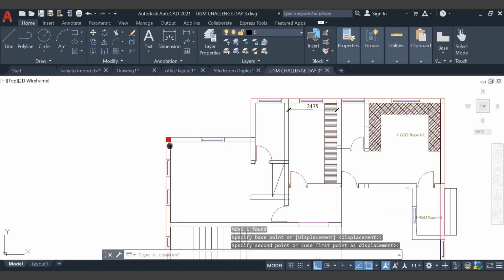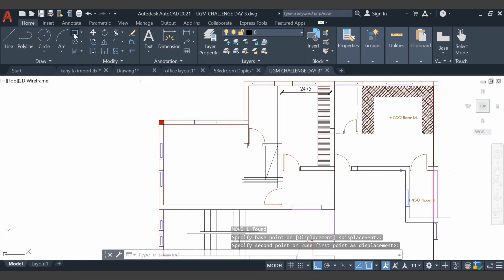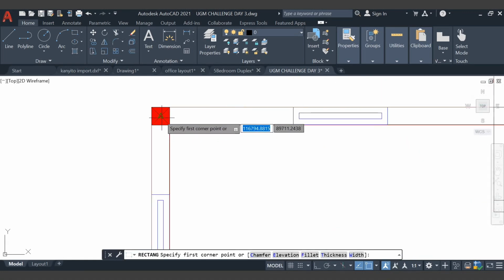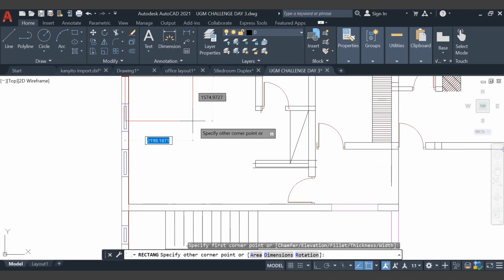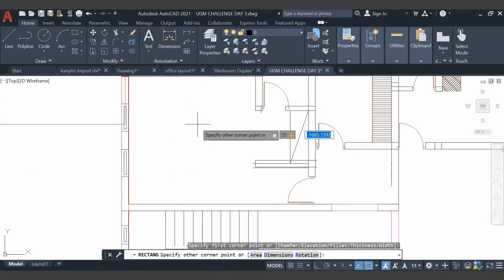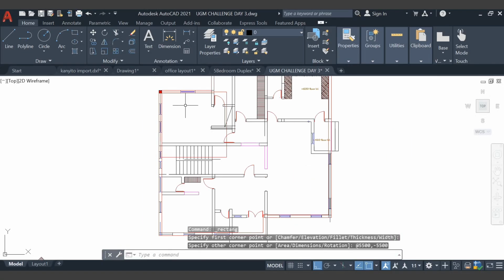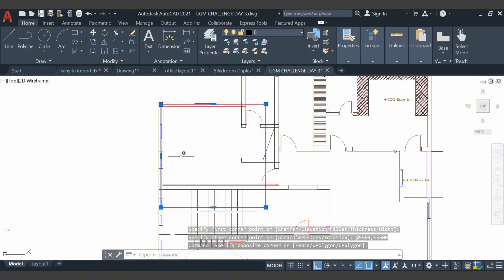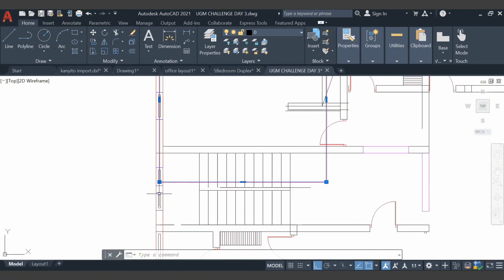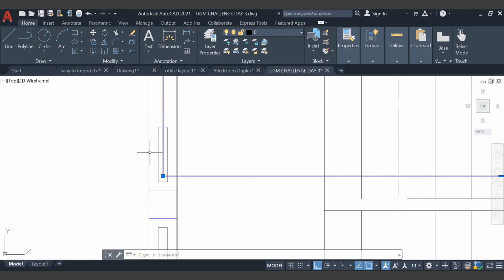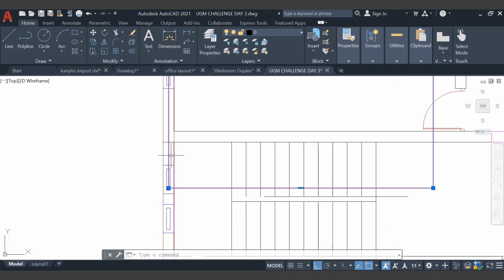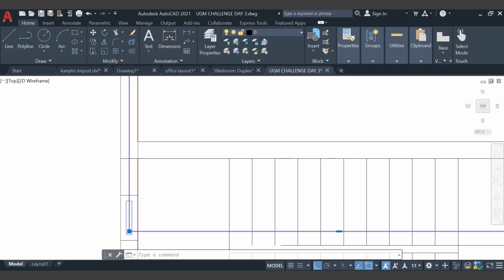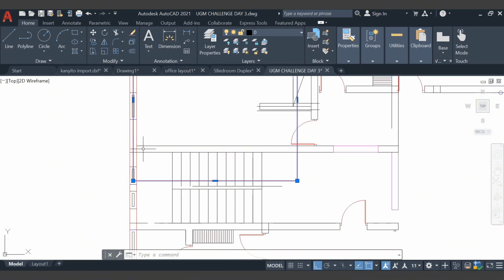Okay, so once I pick out the column, I would model a rectangle which would symbolize a panel for me of 5.5 meters. Okay, so this now shows that if I want to make my beam of 450 millimeters deep, the next column I should place should be around here. But you can see this lands in a window, so I can either place it at the edge of the window, or it looks better here on the main grid, on the structural grid of the design.